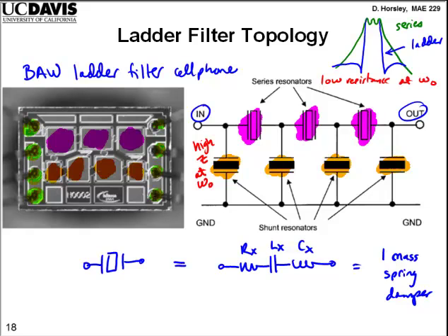This thing is a couple of millimeters across, and so each of these filters is on the order of 200 microns square. And you'll notice that they have sort of funny non-square shapes to them. Part of the reason for this is that they intentionally shape them such that they don't have parallel sidewalls, because with parallel sidewalls it's possible to have acoustic modes that can resonate in plane.